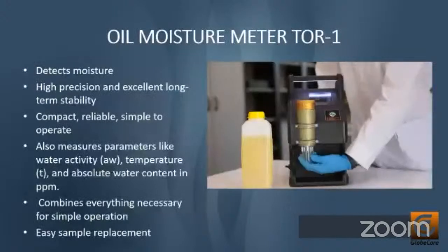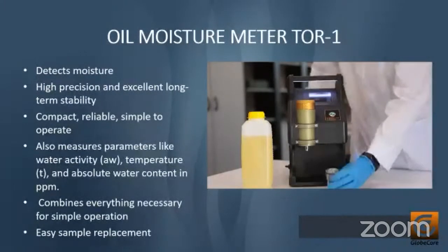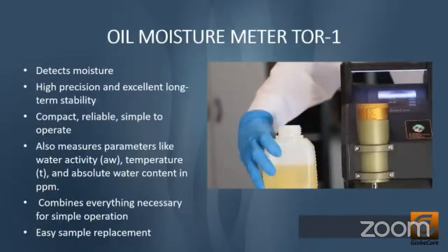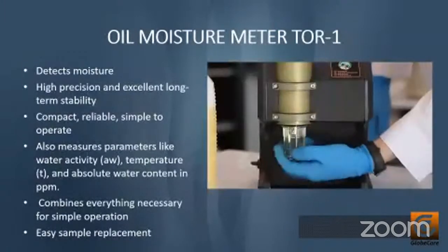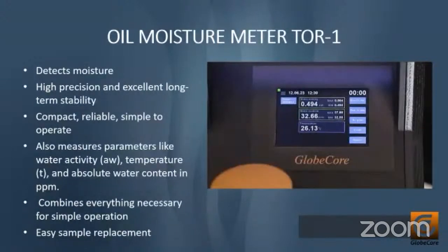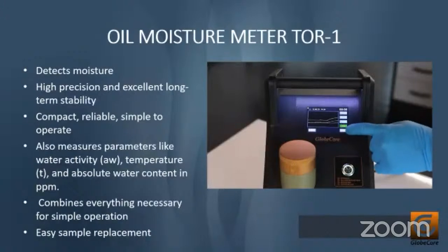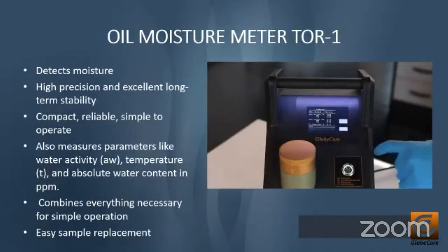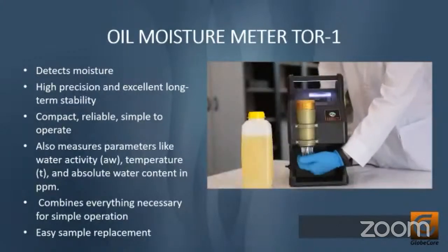All these kinds of equipment are really small and really easy to use, and are a really good complement for work in the field. When you are running procedures of reconditioning the oil or dehydration, the gas in oil, you will need to know if your procedure reaches the desirable values, and that means you will need some equipment to help you understand you are running the procedures with the thermal vacuum machines in a good way.